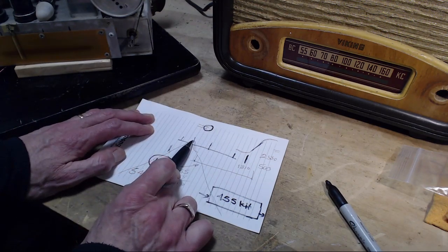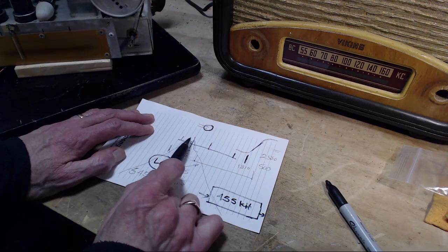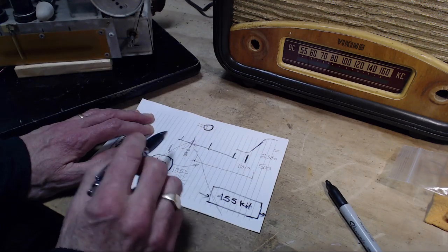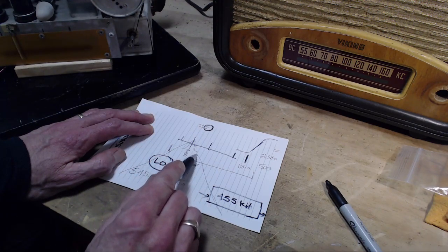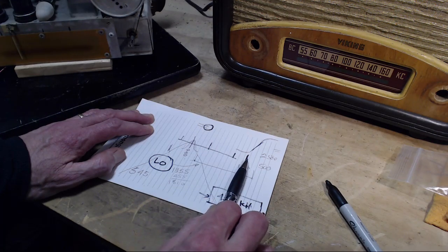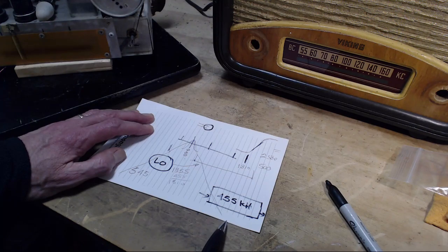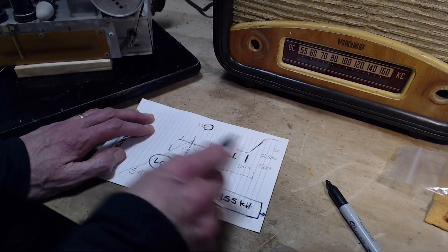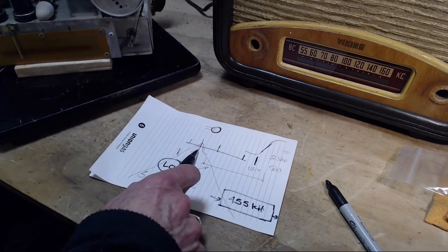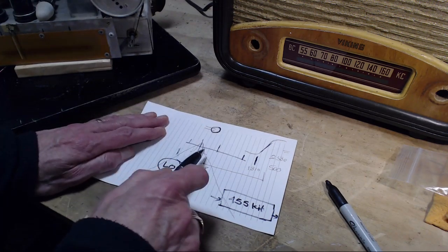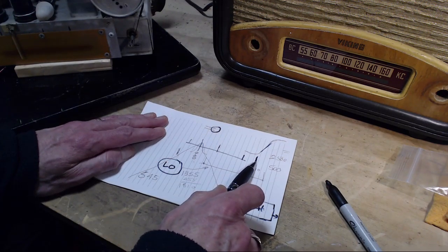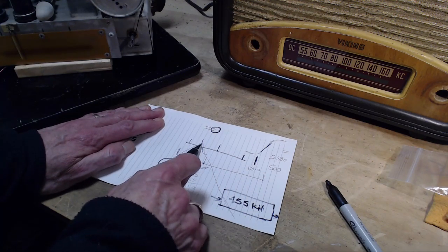So the signal here comes through great. Signal here a little weak, because with the radio tuned here, an adjacent signal here is weakened by this effect in the front end. And by the time you get way out here, this signal is so weakened it really can't get into the front end of the radio. And some radios really focus on this, because the weaker the signal you're after and the stronger the image signal, the more difficulty you might have in hearing this guy.